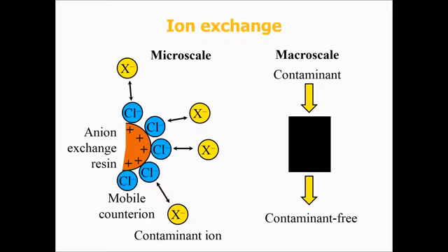That's a polymer bead that's positively charged. So associated with those positive charges is a negative counterion. In most cases that would be chloride. And then that chloride exchanges with your contaminant anion in solution, which could be dissolved organic carbon, could be nitrate, could be other anionic contaminants.